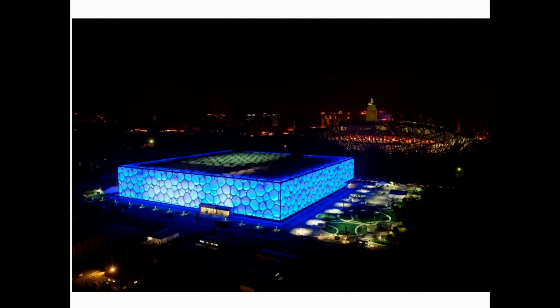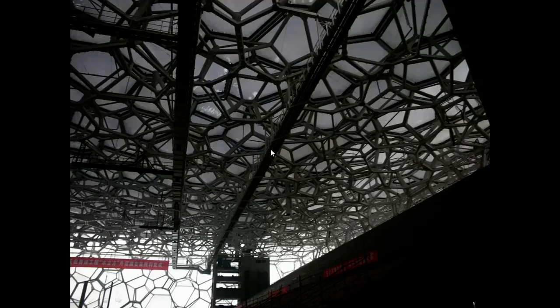You can go a bit bonkers with space frames, as they did for the 2008 Beijing Olympics. This is what was known as the Water Cube, and we talk about it for two reasons. One, these astonishing panels, which are ETFE air pillows, very lightweight panels that skin the building. But it's also a continuous span. The roof is spanning continuously from the walls. Now the whole thing is a dense web of space frames. So it's no longer rational, is it? It's no longer symmetrical. But the principle still applies. It is effectively a space frame.